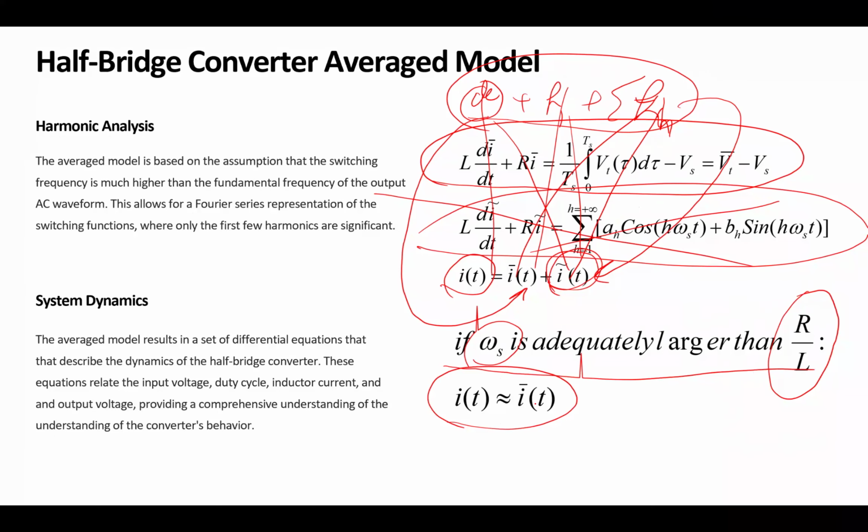Consider this. You have a natural frequency in your system, and you input a signal with a certain frequency and its harmonics into that system. The harmonics are higher than that fundamental, multiple integers of it. Now if the natural frequency of your system is much lower than your fundamental frequency, the lowest input frequency, then you won't see any resonance in your system. Is that clear to physics?